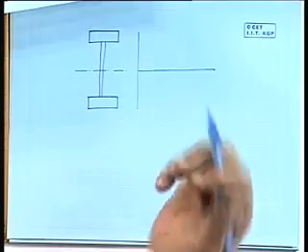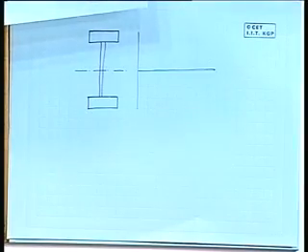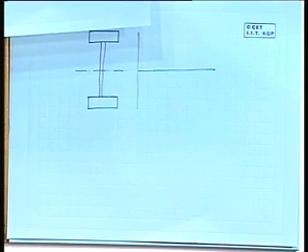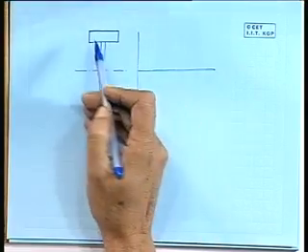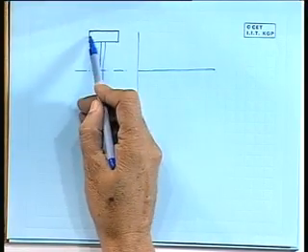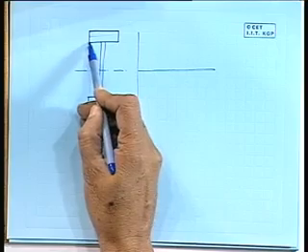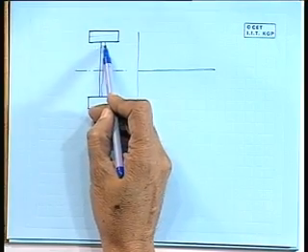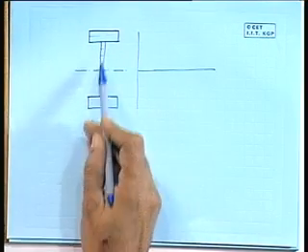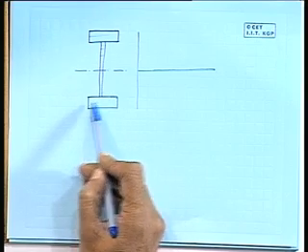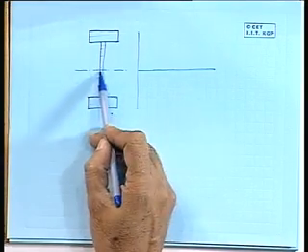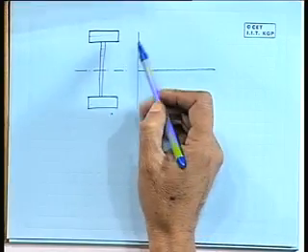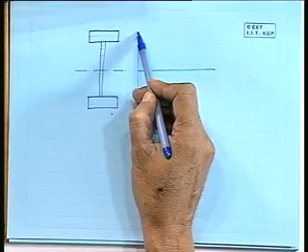I am considering a uniform cross sectional I beam, and therefore, the moment of inertia of this about its neutral axis is also constant at that particular section. b changes from this place, it is this b, and as soon as you cross this junction, this becomes the b, and this continues till you come to this place, and then this becomes the b. Okay. So, when you try to find out what is the stress here, the stress here will be 0,